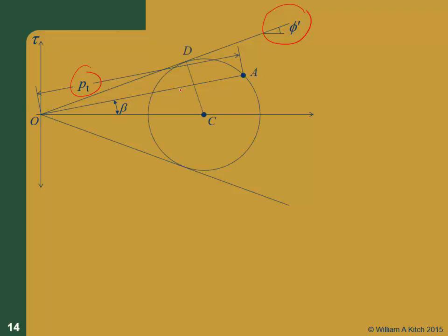So we still got our Mohr circle. We still have our Mohr Coulomb diagram. This is beta, so that's the angle, the point where PT is acting at point A. We're going to draw our Mohr circle in. There's some shear stresses on that, but we're going to know this point because we know this direction, right?